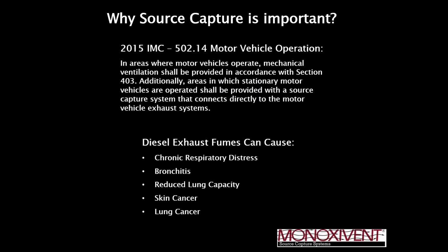So why is source capture important? Well, if you think about the exhaust that comes through, in particular diesel engines, the particulate in diesel exhaust is a known carcinogen. It's a known cancer-causing agent, right? So we want to make sure that we're not breathing that in. And there's a lot of other things that occur with your respiratory system, right? Bronchitis, reduced lung capacity, all of that is a byproduct of the diesel exhaust. So we want to make sure we don't breathe it in.